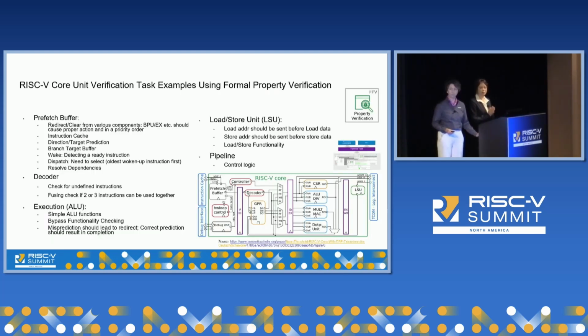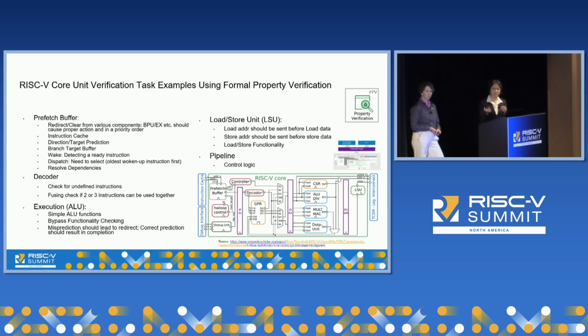And then look at the RISC-V core block diagram. You see these color-coded, the 7 blocks, it's really cool. They are identified as well suited for formal, where you can build a unit-level formal verification environment for these blocks to verify the functionalities. You can build a formal test bench with SVA assertions and auxiliary logic to set up assertions and assumptions of your environment. Then you use formal tools such as Synopsys VC Formal, the FPV app, formal property verification app, to verify these design functionalities.